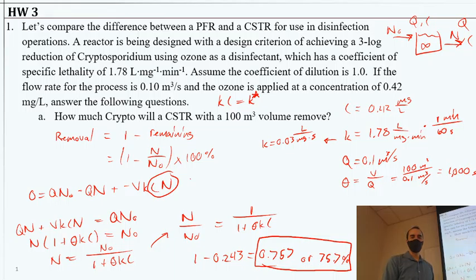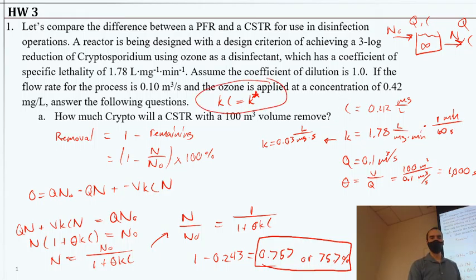One thing that can confuse that is the C here and the N. The C is going to be constant because we're assuming that the ozone stays constant throughout this process, and so that's why it might be worthwhile just to substitute in a K star that accounts for both of those, and carry that through, and then it feels just normal like any other thing we've ever done. So you can do that, and you ought to remember this relationship here when it comes to disinfection, because that's going to be important. You're going to have to do that sometimes, or go between them.